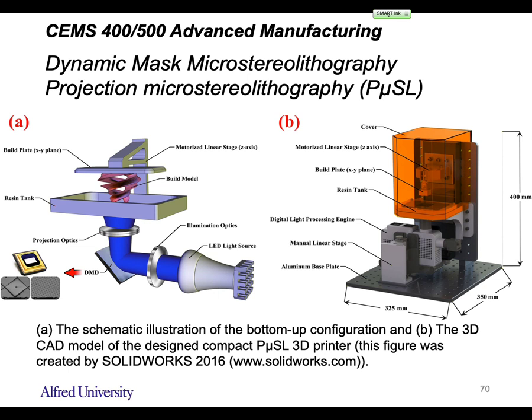So with that, you can design a pretty low cost machine, but because of the cost of the DMD, it's pretty expensive, right? For 4K DMDs, that element may cost more than $1,000. So this setup can be quite simple, but the machine is not that low cost. And also the lifetime of those projection-based 3D printers is limited. You can only use it for probably 20,000 hours or 2,000 hours, depending on the lifetime of your DMD.